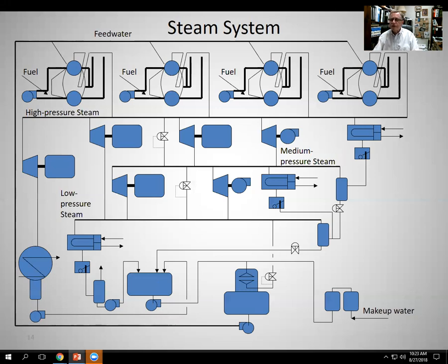And here is, I think, the last one of these, and it's all the same sort of stuff. What we have added over here is a condensing turbine. This is taking high pressure steam, and this device is indicated to be a condenser, which could operate at very, very low pressures, even sub-atmospheric, in order to get the biggest pressure drop possible across the turbine, which will maximize the amount of power we can get out of the turbine, or electricity out of the generator.